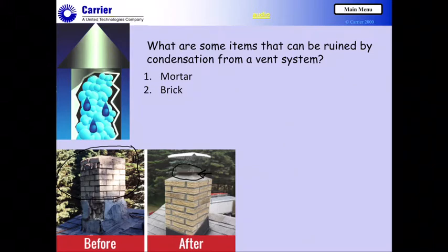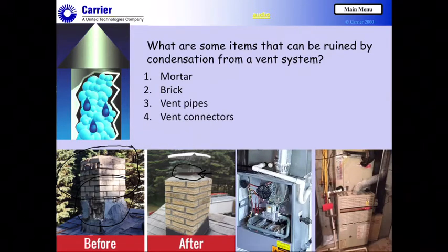But those are generally put in as 2-foot long pieces, and they'll use mortar in between those pieces. When those start to leak, the moisture will start to leak out of them, and then they'll deteriorate and erode this entire vent system. As you can see, this one's really in bad shape, but that is a legitimate issue.